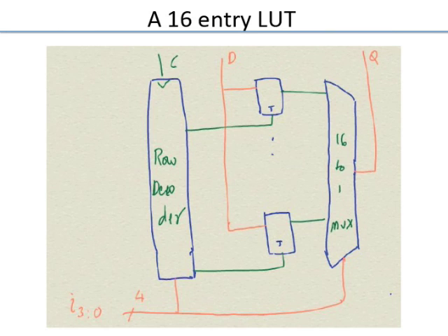So what is that clock? This should have been a write enable signal. And the clock is also there because I've used a latch type structure out here. A latch means it is transparent for some time and then it is opaque. So when I write into a particular entry in the memory, this word line has to be like a pulse.